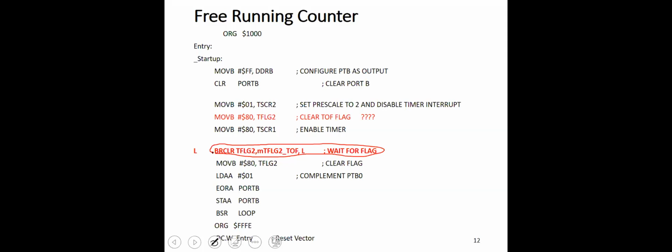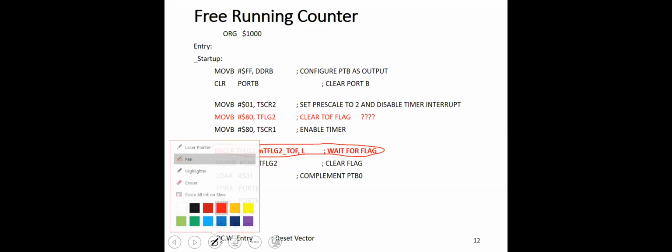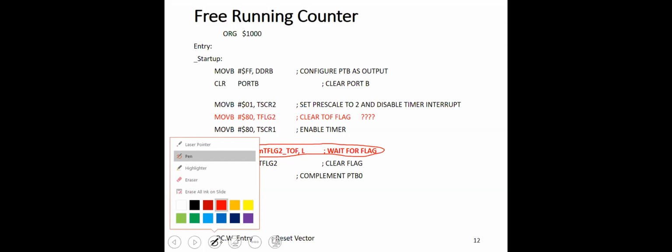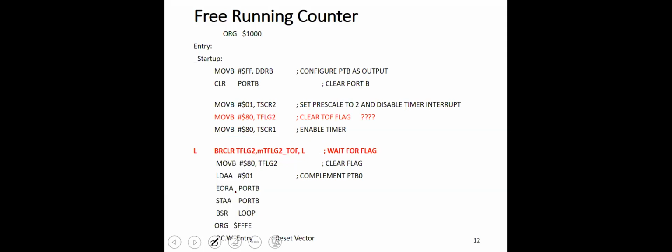It is not the hardware timer. So the hardware timer is still running and counting, and the CPU will service the interrupt. So this is one major advantage of using hardware timers: they are more accurate in case interrupts are enabled in the system.